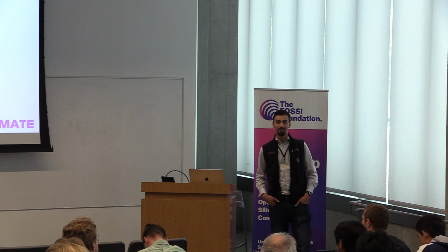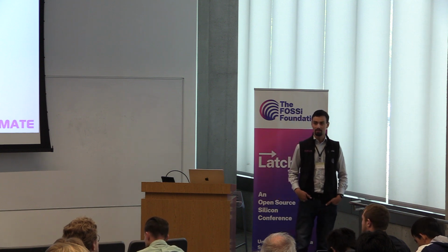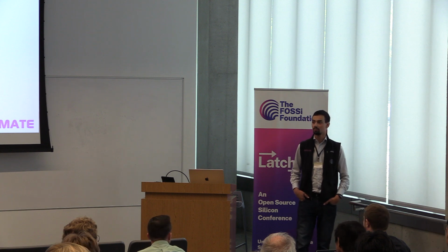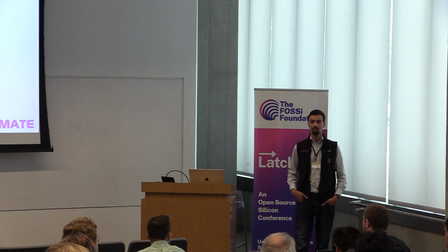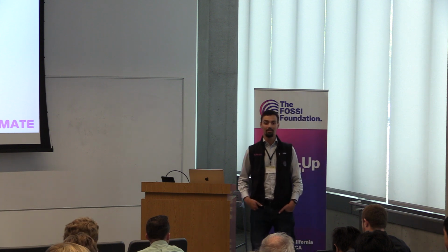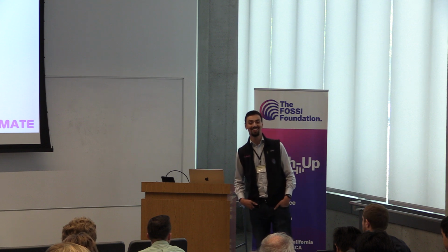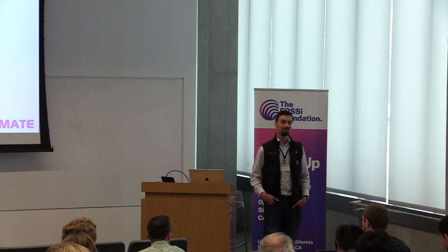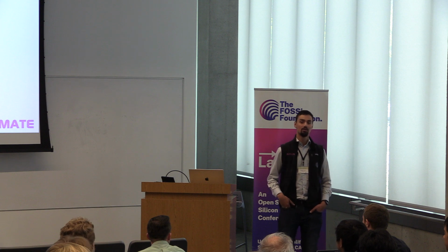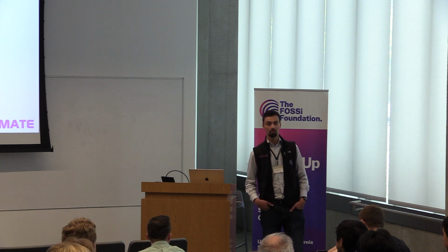I wouldn't recommend it for sign-off checks, just because they can give numbers that are not what you would expect. And honestly, if you're using open source tools for silicon, I would leave a lot of wiggle room. I would make sure you have a lot of slack at the end of the day, rather than a little bit, because these aren't necessarily well qualified across hundreds of commercial users like the commercial tools are.